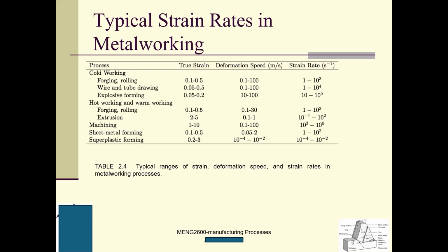Different materials have different recrystallization temperatures. Hot working means that the operating temperature at which you are operating the machine is above the recrystallization temperature. Usually for hot working you need to elevate the temperature. Cold working we usually just do at room temperature, right?